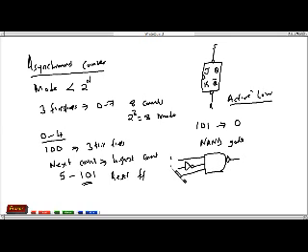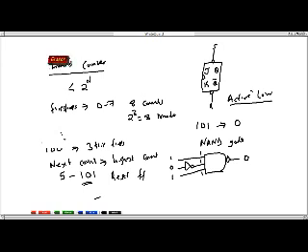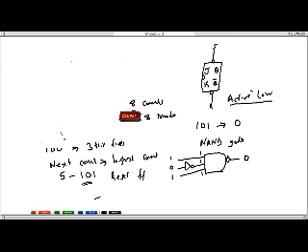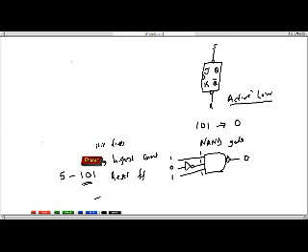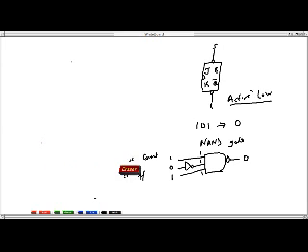So this is 1, 0, 1. The inputs to the NAND gate will be 1, 1, 1, because the NOT gate inverts the 0 to a 1. And you can see 1 and 1 and 1 is 1, inverted, we get a 0. And we can use this 0 to reset our flip-flops. So that at the end of the day, we have our flip-flops configured just like in a mod 2 power n asynchronous counter, but we make use of the NAND gate to reset our flip-flops.